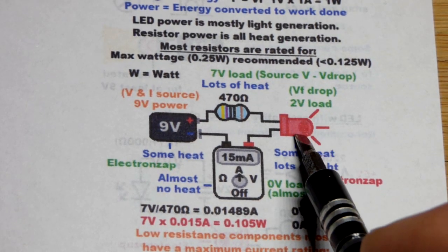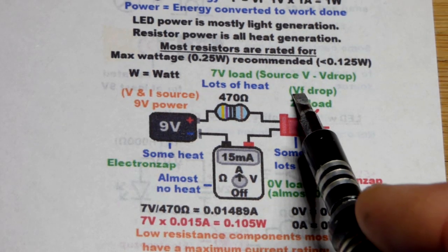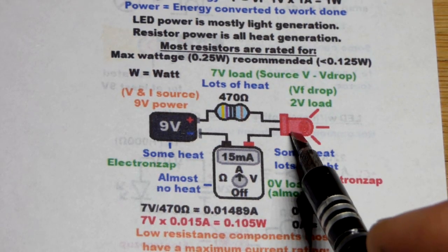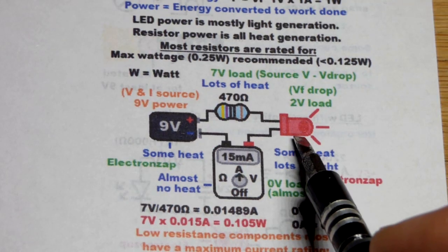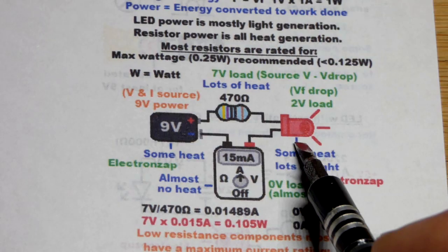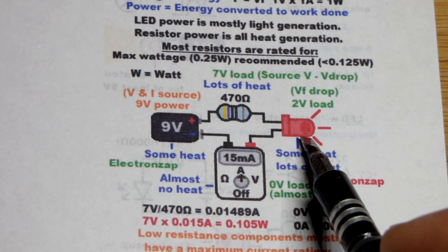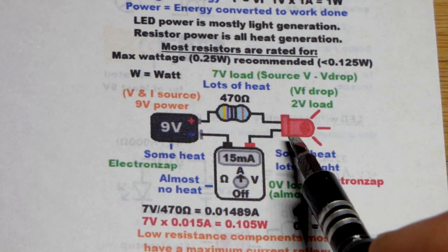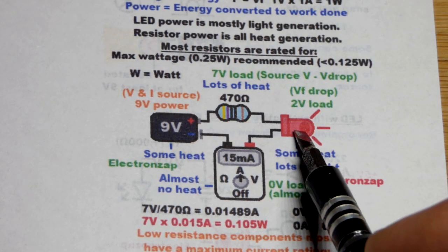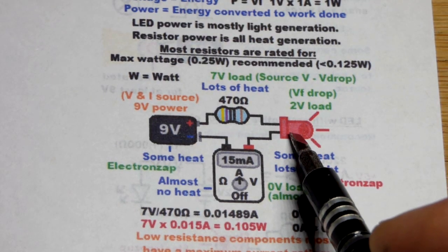So semiconductors drop a certain amount of voltage, usually, not always, but if you hear voltage drop, that means forward voltage, when it's forward biased, the way it's made to conduct. Reverse bias, that would mean the LED is in backwards, and I think they block up to 10 volts, maybe, and then they'll have a breakdown voltage where they'll conduct even though they're backwards. That destroys the LED. You don't want to do that with LEDs. There's other diodes for that kind of stuff. But if you put it in backwards with 9 volts, it's just not going to light up.